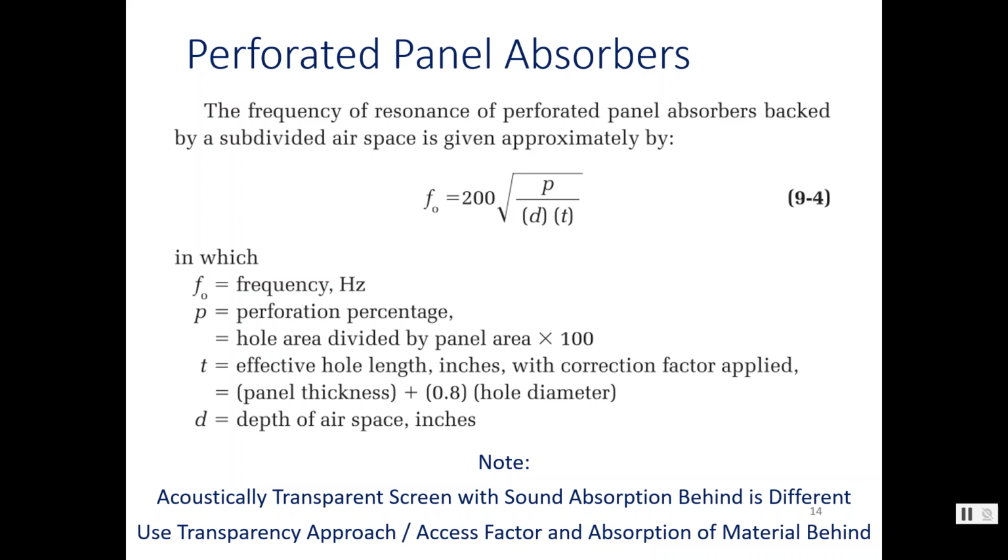Like you might be designing, say you're designing HVAC equipment, and a lot of times they come with a casing that's intended to attenuate sound. So you can put this close to the property line and still meet the noise ordinance. But inside of that, in some cases they might just line it with fiberglass type of insulation, the fibrous insulation.